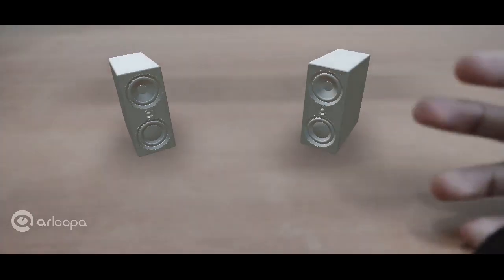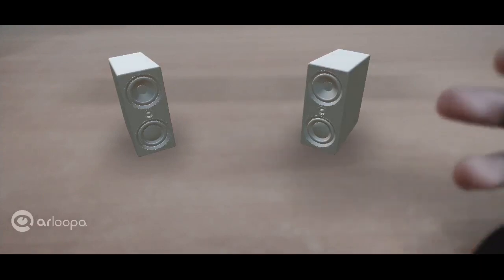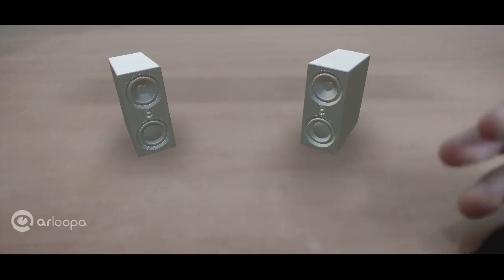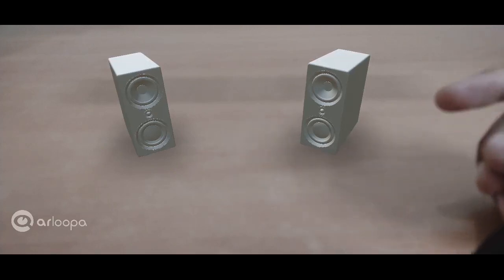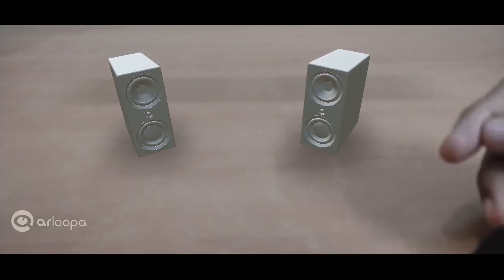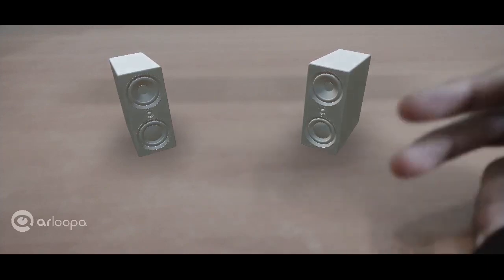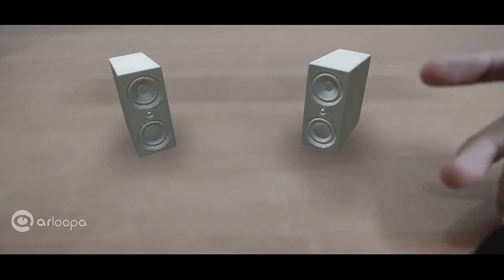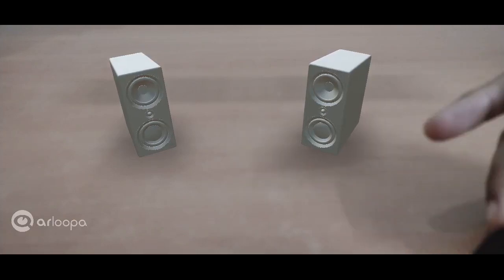So every single component has to have a flat frequency response so that the final sound has a flat frequency response. If each and every component offers a flat frequency response, they'll not distort the sound in any way. They'll not boost or cut any frequencies, so that the final output is flat. But if any component in the chain has a non-flat frequency response, that's going to show up in the final sound by boosting or cutting certain frequencies.